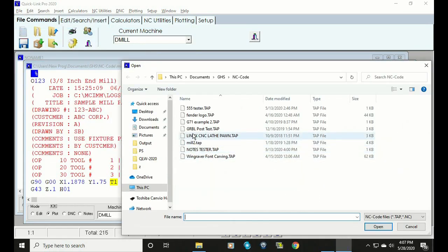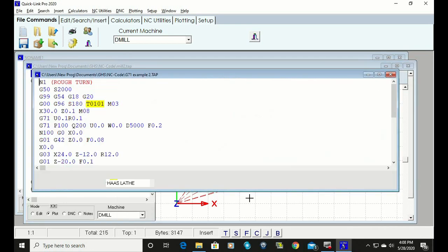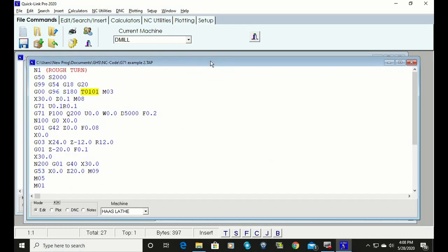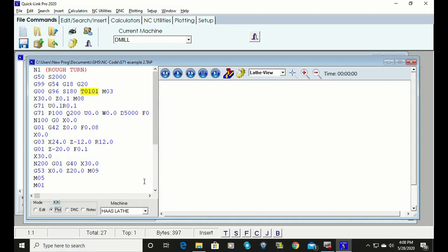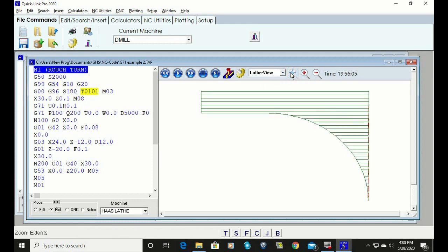Here I'm going to open it up and mention while I'm at it, one of the features of the new version is that it will plot lathe canned cycles. It always did the threading, but now it'll do the facing and turning rough cycles. It just gives you some lines to show you where that's going to happen, and just by virtue of the fact that it shows you the shape, you can see that you basically have your outline of the part you defined correctly. And see here, I'll just do a quick one of pulling this one up.